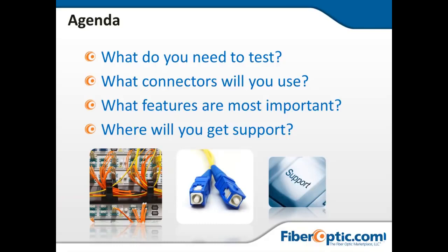So what you will need to perform your test, and what type of connectors will I be using? So whether they're SC, as pictured on the screen here in the middle, you need to make sure you have the same connection when you're connecting to the OTDR, or at least your launch box. Really, it would be your launch box in this case, and we'll get into that a little bit more in detail. But what connectors do you have on the end of your fibers? The fiber under test is going to be an important thing.